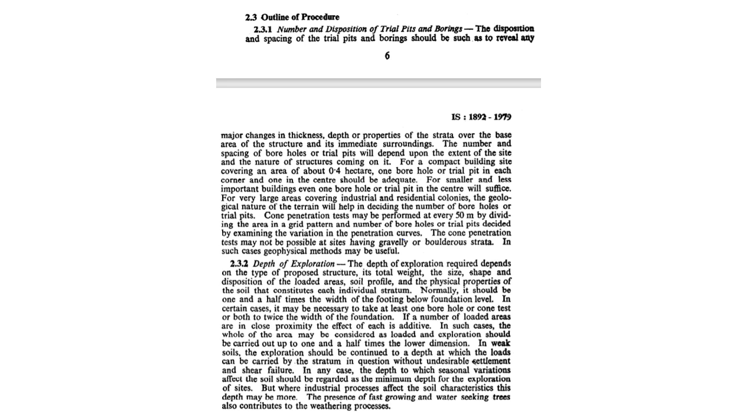And then see, these trial pits actually can even be taken during your site reconnaissance itself, because, as I said, the work can be done manually, so it doesn't require any very laborious instruments or anything. So you can take the trial pits during site reconnaissance itself. So you will get an idea about the soil stratification there itself, or the type of soil, at least up to the 2 meter or so. You will be able to understand the type of soil that exists.